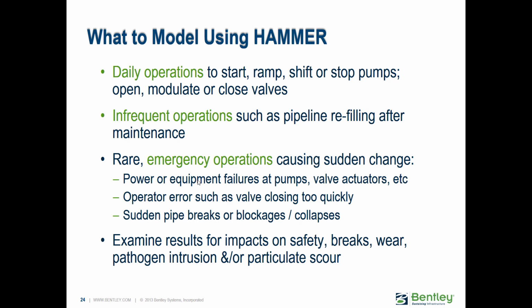And then you'd model infrequent operations like pipeline refilling after maintenance, and that's a little bit of a complex topic when you're introducing that quantity of air. It's a bit of a specialized case. You would have a discharge to atmosphere at the end of your system with an initial air volume, and you might be analyzing what happens when all of that air is expelled. So that would be an infrequent operation.